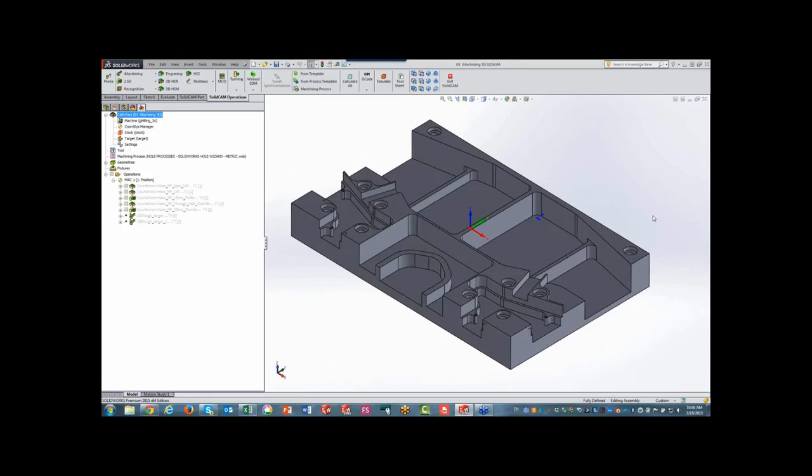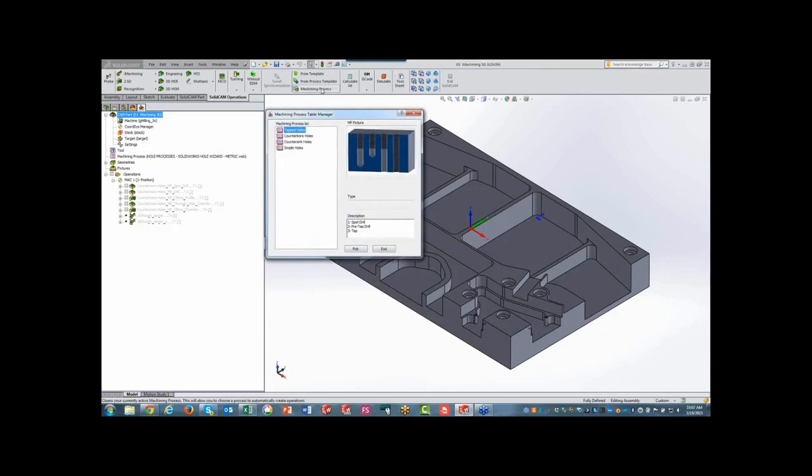Well, aside from iMachining 3D, we also have a beautiful tool that recognizes the SolidWorks hole wizard parameters. In other words, the holes that we created in SolidWorks using the hole wizard are automatically recognized if I use them in a machining process. And I'll actually do it for you because it goes really, really quick. Machining process, you can even time me how long it's going to take to program this part.